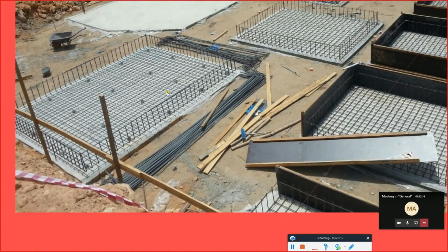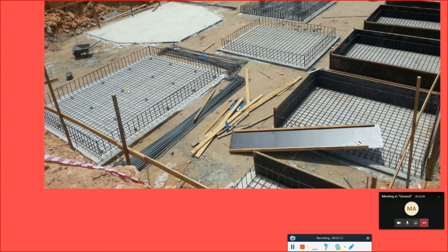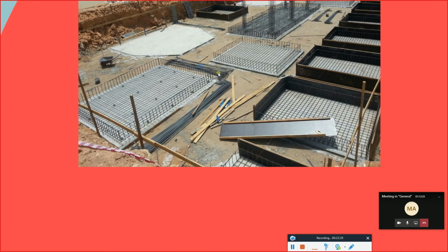Okay, so the first thing that we need to do when it comes to foundation, we need to put the steel. Why don't we put the formwork first? Because it's very hard to make the formwork and then inside the formwork make the steel. So what we need to do first is put the reinforcement. After we finish the reinforcement, we are going to go for the formwork. So for the foundation, reinforcement is first, and then the formwork.